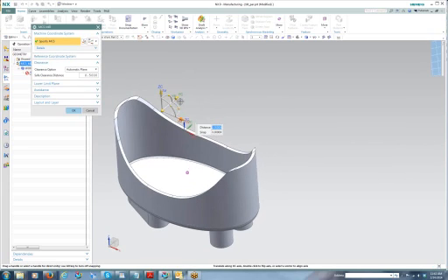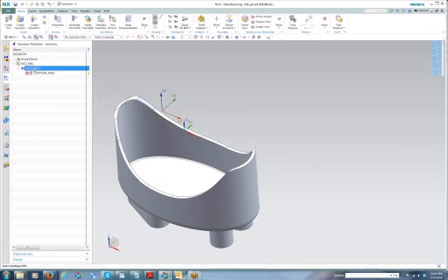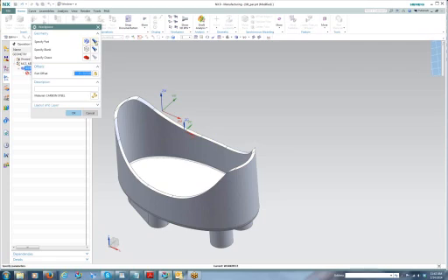So there's just a lot of flexibility here to rotate or move this coordinate system to the place it needs to be. Then I've defined my workpiece. It's just the block as you see it. And I can also define a blank here, or check surfaces, which could be a vise or your clamps.